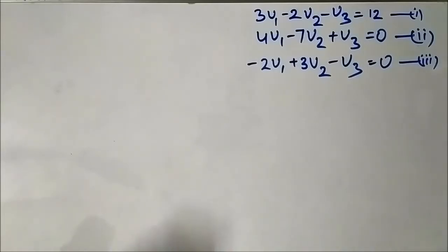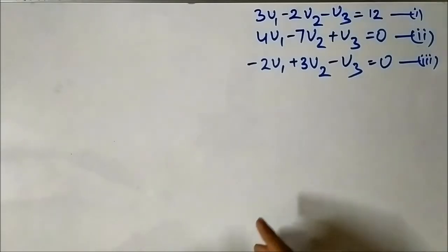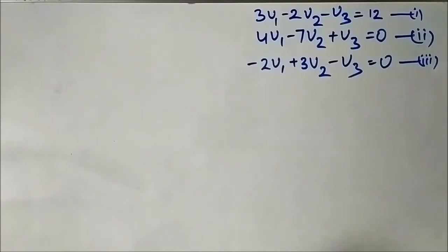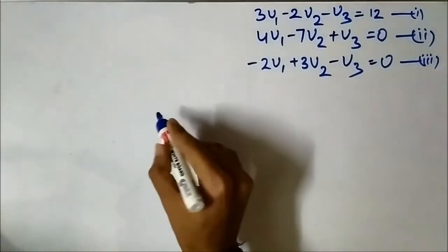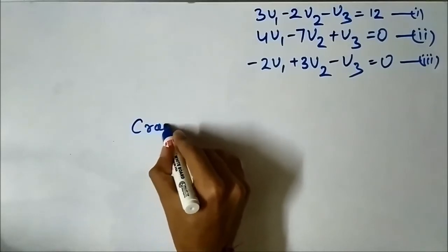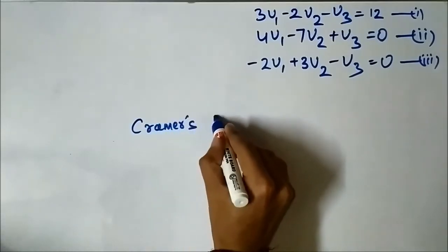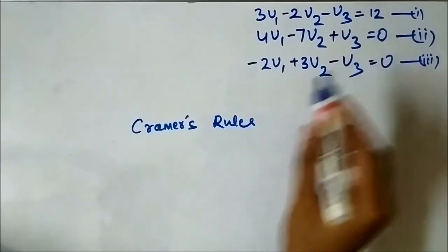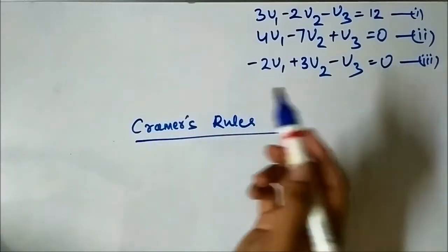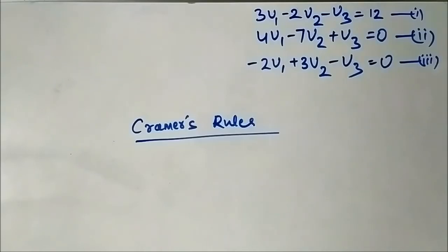Now if scientific calculators are not allowed and you have to do it by yourself, then there are a few approaches. First one is the variable cancellation method, which we used in the previous video related to nodal analysis, where we solved a problem of 2 variables, nodal voltages V1 and V2, using the variable cancellation method. But the most useful method is Cramer's rule. It involves converting these equations into matrix format, then evaluating the determinant of that matrix and then calculating the value of the unknown variables.